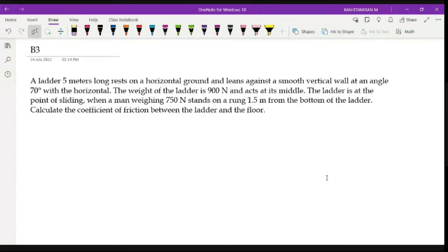Whereas the previous problems, block friction and wedge friction, are related to concurrent forces. You don't have any moment; we always say sigma Fx 0 and sigma Fy 0, and that's it. In a ladder you also deal with moments, because you have non-concurrent forces.